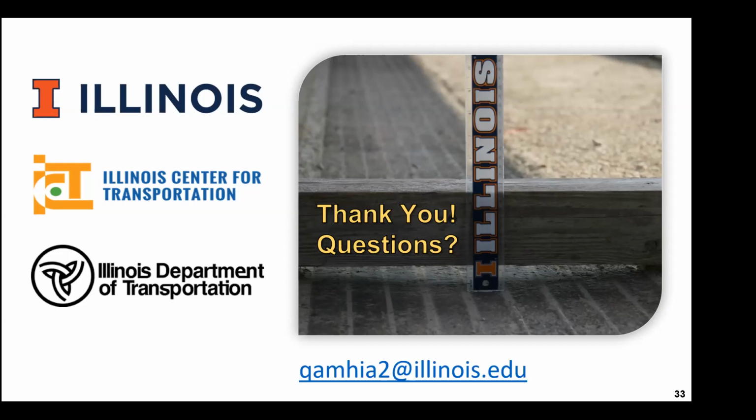Right. So that's the idea behind, if you remember, I mentioned in one of the slides that we were limiting the gradation or the grain size distribution of the samples that were tested with the recycled concrete aggregates to 3/4 of an inch or less. And that's actually a boundary effect criterion that is usually checked with AASHTO and ASTM procedures, is that you have a limited sample size. Let's say this is a 4-inch size mold or a 3-inch mold size.